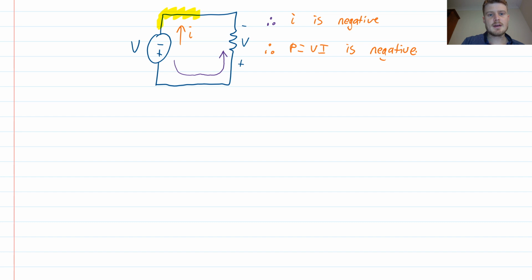And similarly over here, so the same voltage and the same polarity on both sides of this circuit because those nodes are just shorted together. So that's the direction of positive voltage across that resistor. But then my current was defined as flowing, if I continue it around, it goes this way and then it comes down here. So my current is defined as entering this way. And so from the resistor's perspective, current is entering the negative terminal. And so I will get a different behavior here.